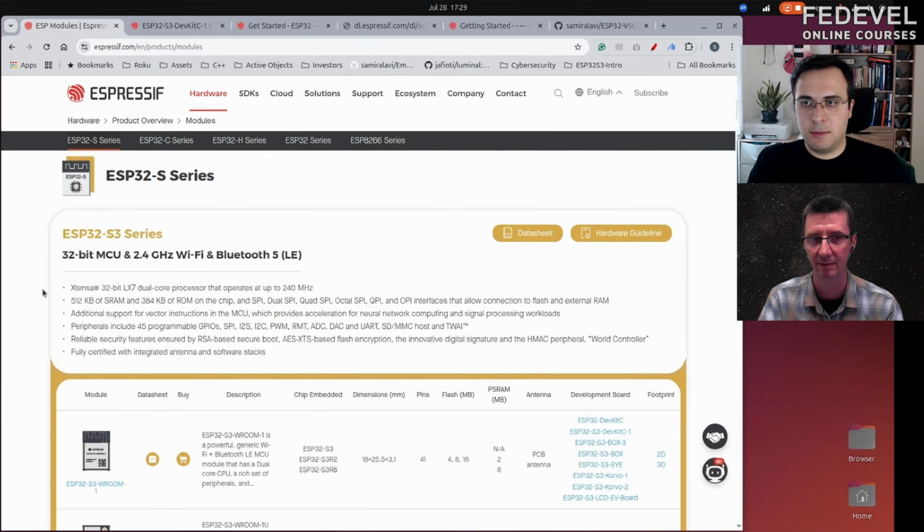We will go through it in the next few minutes, but Arduino gives you a precompiled version of the ESP-IDF SDK with a predefined configuration. That configuration is fixed at the build time of the Arduino library, which was meant to be general purpose, but different applications require different configurations. You can still use Arduino with ESP-IDF, but you need to build it yourself, which means you need to know how ESP-IDF works.